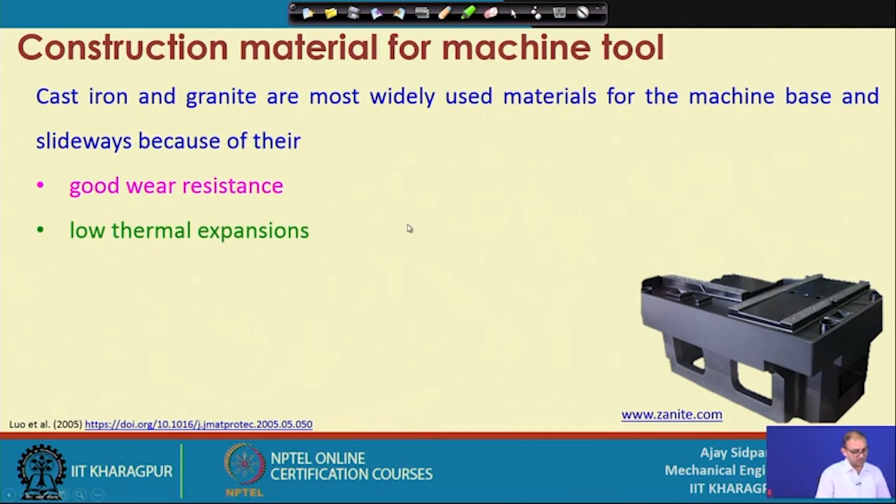conventional lathe machine or milling machine, generally you do not provide the envelope on the top. So, because of that, whenever you are operating in a summer or you are operating in a winter, the temperature difference is more than 30-40 degrees in some of the locations. So, because of that, you may not get large variation in the thermal deformation because of the climate temperature difference.